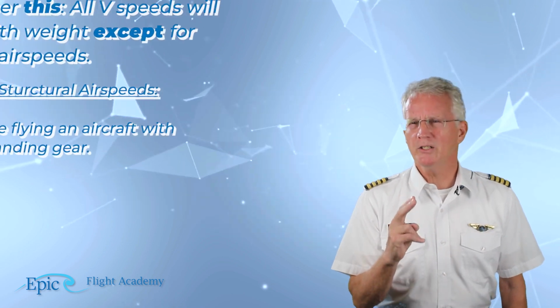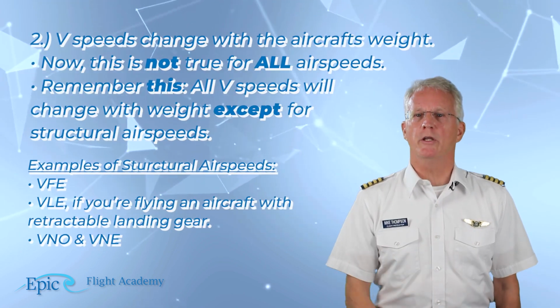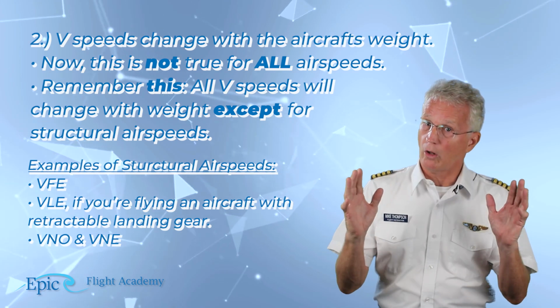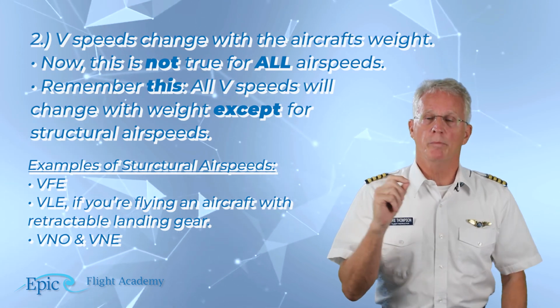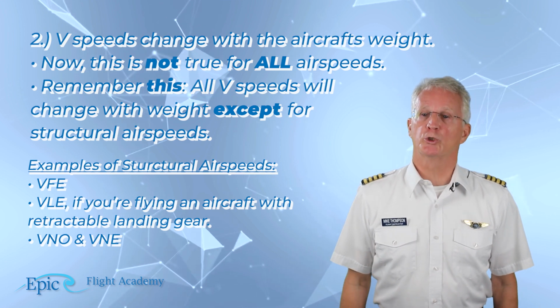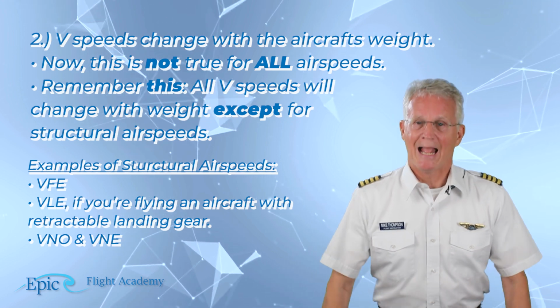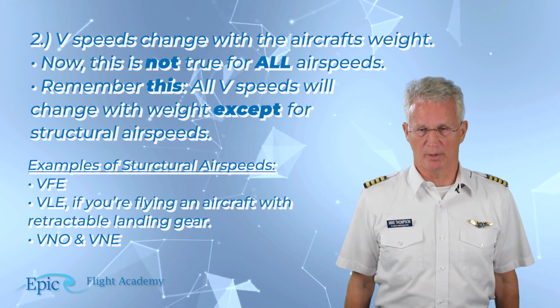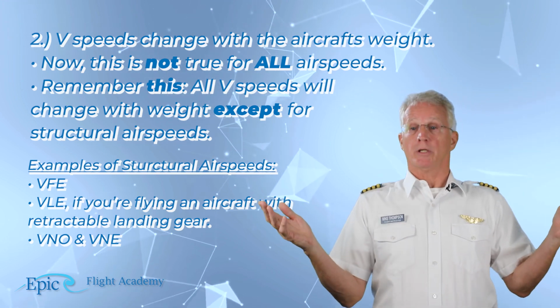Number 2, V speeds change with the aircraft's weight. Now, this is not true for all airspeeds. Remember this, all V speeds will change with weight except for structural airspeeds. What are some structural airspeeds?